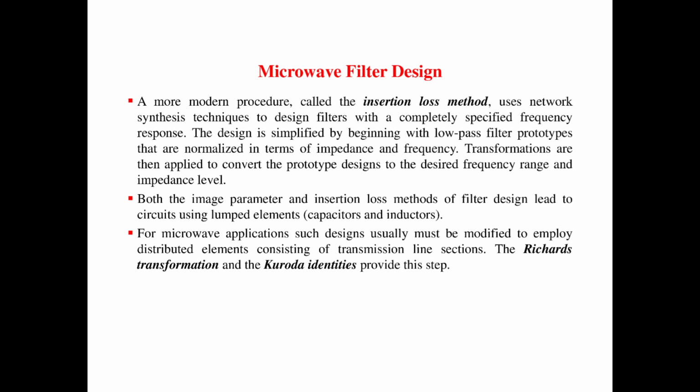A more modern procedure called the insertion loss method uses network synthesis techniques to design a filter with a completely specified frequency response. The design is simplified by beginning with a low pass filter prototype that is normalized in terms of impedance and frequency. Transformations are then applied to convert the prototype design to the desired frequency range and impedance level.